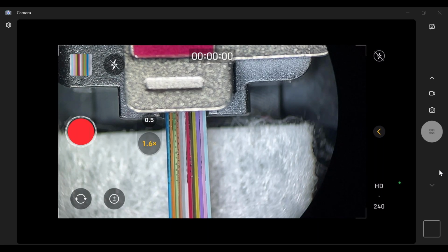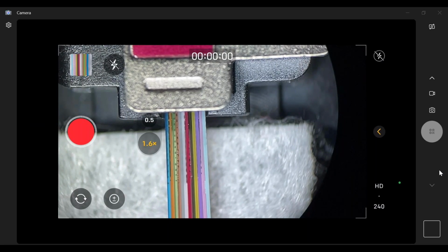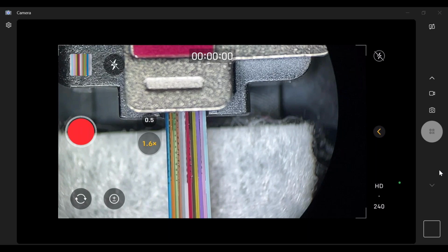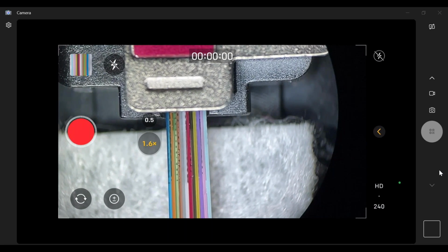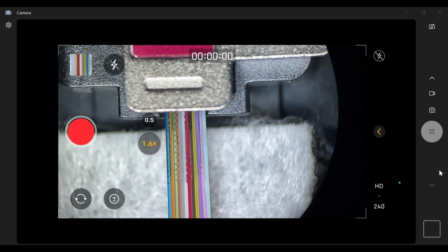As I said earlier, if you're doing 200 micron to 200 micron, left and right side, the best possible scenario as far as accessories would be the 200 micron pitch V groove versus the 250. If you can avoid pitch conversion, I highly recommend that you go down that path. The main reason for it is ease of use, just simply a better decision, and you'll get higher consistency, higher quality, faster splicing times.